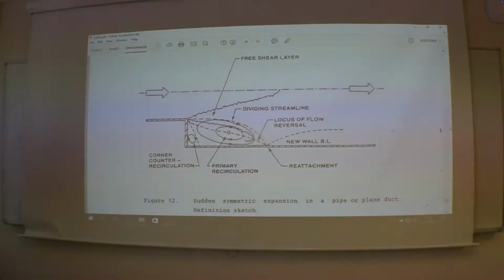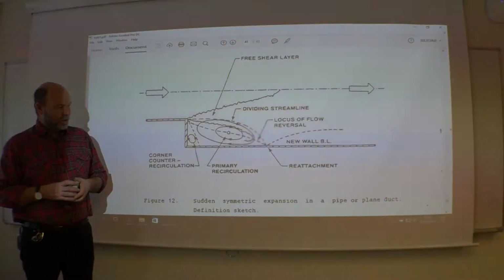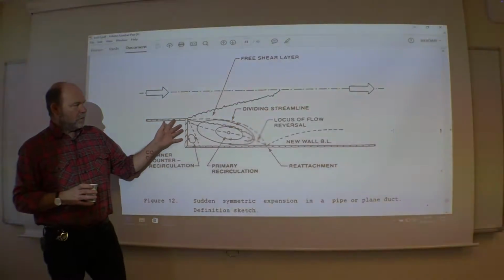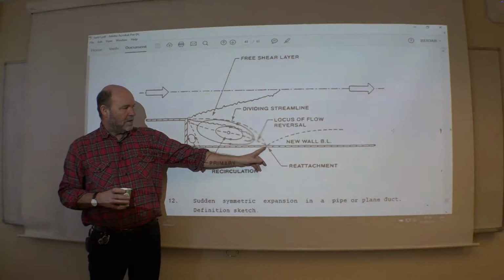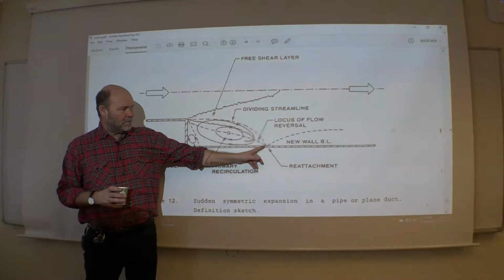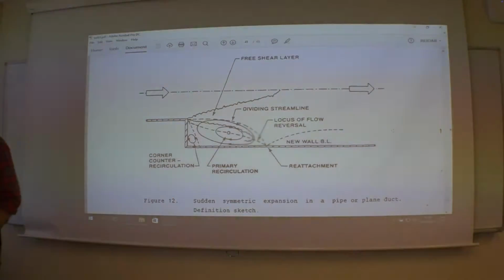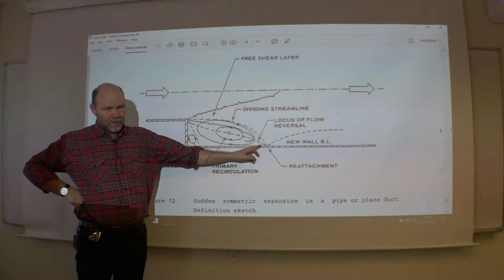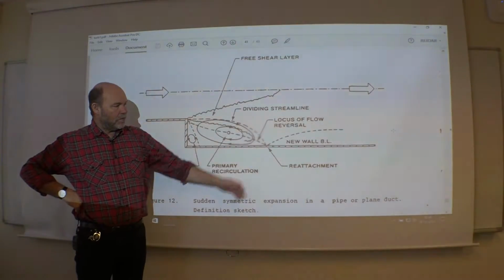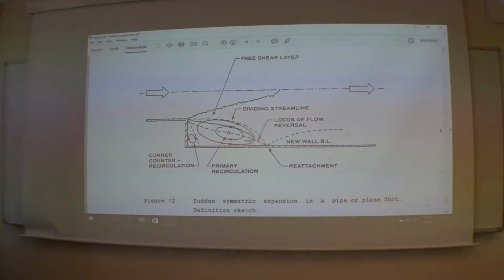Another popular test case, sudden expansion, backward facing step. And this is also a classical problem for a standard K epsilon model. If you play around with this problem here, finding this reattachment point for different Reynolds numbers, then you can get any result you like actually by just playing around with the meshes. How well you resolve the boundary layer here, you will get a different answer every time if you use the K epsilon model. Very bad model for this problem.